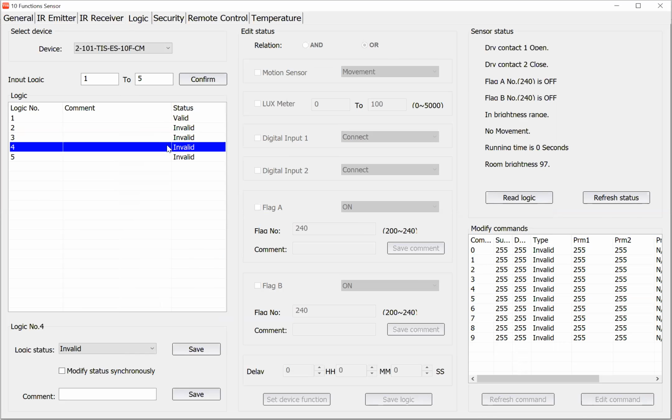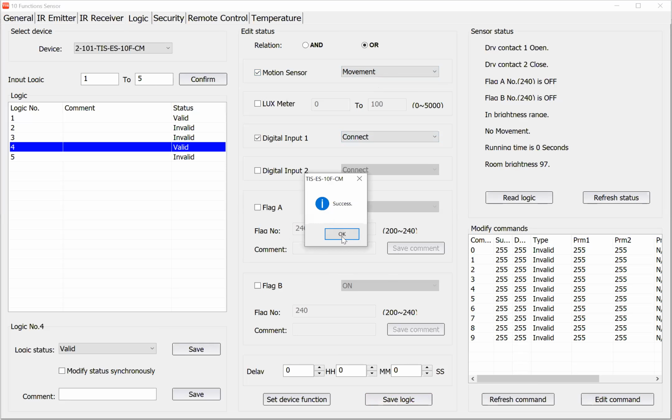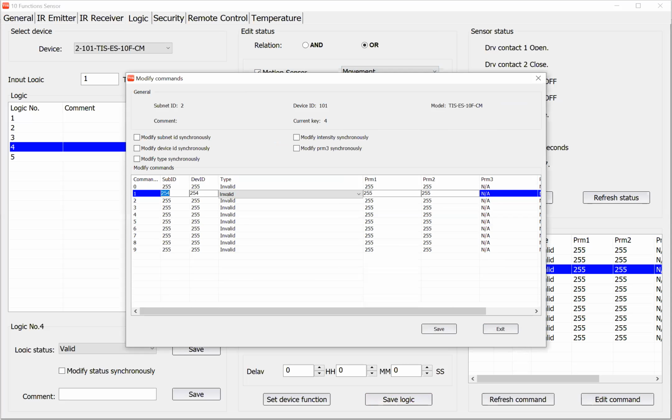And also you can program many other things. If you want to send any command, such as a cooling temperature, imagine we want to program if the door is closed and we have motion, then turn on the AC on cool and 22. How do we program? Very simple. Subnet ID and device ID of my HVAC, panel control, AC power on.